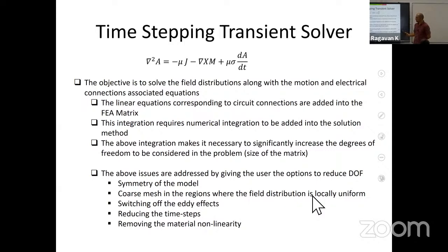One thumb rule that can be used is that you can keep 40 time steps in one cycle, right? If that doesn't address the problem in your case, then the next thumb rule you can use is to keep on reducing the time step, keep on making it finer.